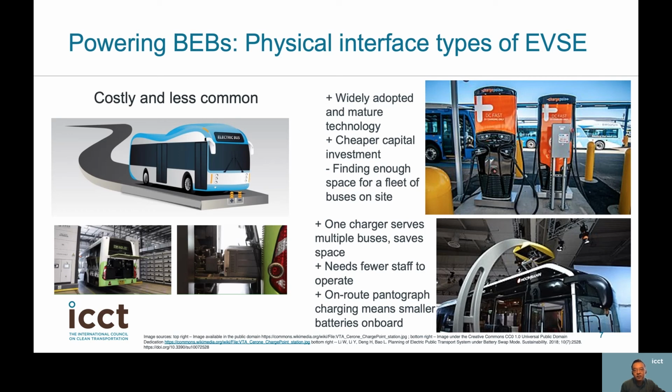Overhead charging is another method of conductive charging. Overhead charging equipment typically uses a pantograph where the moving parts are on the bus, or an inverted pantograph where the moving parts are on the mast. There are several providers of pantograph charging technologies today, and such systems are offered as an option by European and North American e-bus producers Proterra, Solaris, VDL, Volvo, and Van Hool.